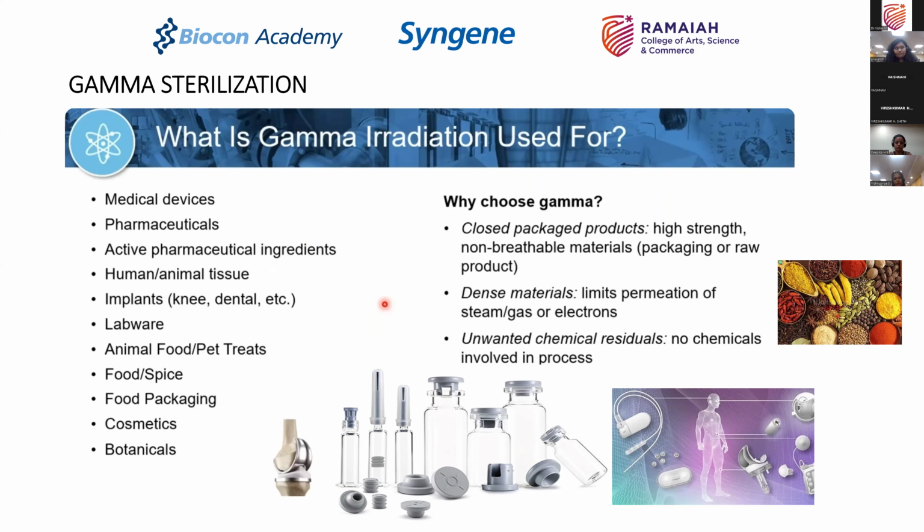Always go by the sterilization decision tree, eliminate the thing, as we said. The first choice is, can you terminally sterilize something? If you can, then go, do not choose an aseptic process. If you have to use an aseptic process, then you have to worry about the components used in it, and you may have to use some of them through steam sterilization, some through depyrogenation or heat based sterilization, and then of course, if there is no other choice, gamma irradiation.